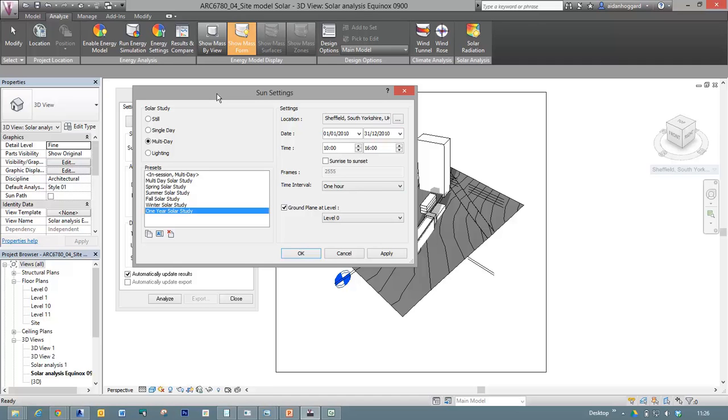The second one, about getting some passive heating from the sun, you may decide, well, I'm only interested in that in winter, or perhaps I'm only interested in that in the morning, because what I don't want in the middle of summer is lots of heating in the afternoon. The third one, about overheating, again, you might decide, well, in winter I'm not worried about overheating because the air temperature will be cold enough outside anyway. And so you need to consider what you are interested in. Why are you studying the radiation?